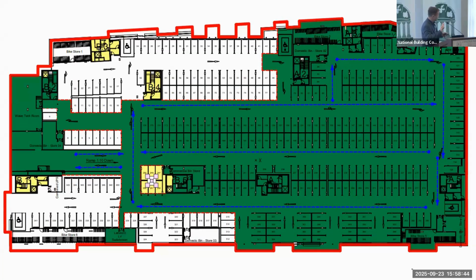That is a generic example of one where on the right-hand side you have a building over, on the left-hand side you have a separate building over. You're looking to hand over the right-hand side first, so you're going to hand over the section of the basement below that. But up here in the top left, you've got water tank rooms, sprinkler tank rooms, switch rooms, all these plant rooms that will be feeding the building you're handing over. That means they need to be included in your phase 1 handover.